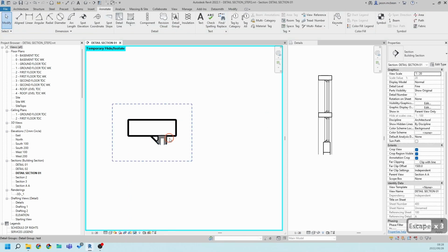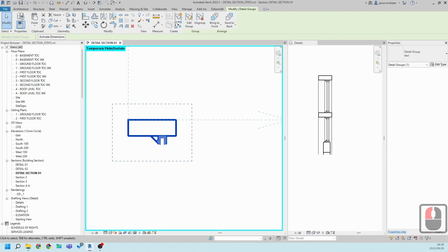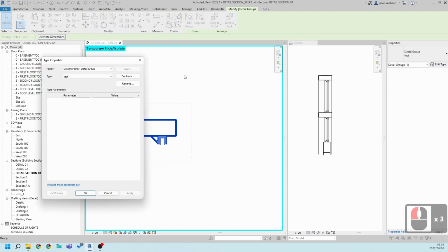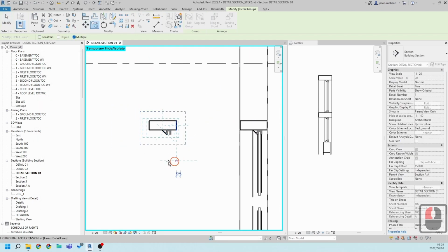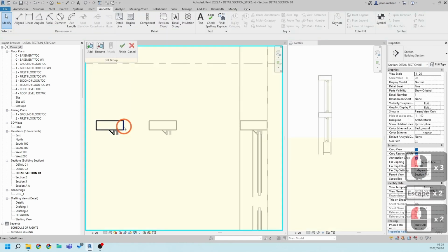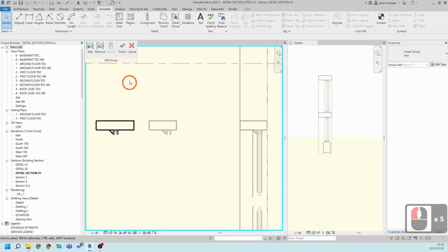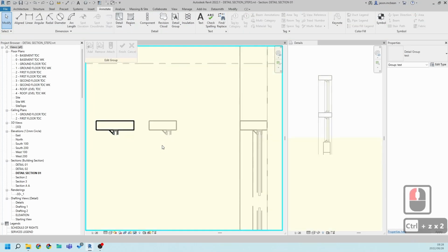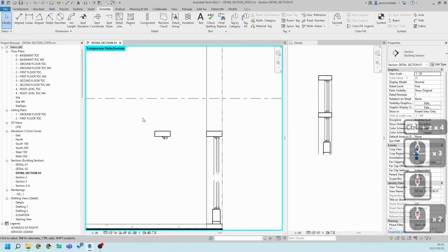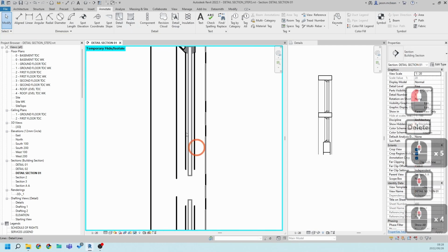In addition, just remember, if you want to duplicate this and make a new group, you'll need to go to duplicate, because if you put the same block in again, let me just show you this, copy, whatever I edit in here will affect this. So you'll need to duplicate these if you want to make duplicates, or use the same type of information.